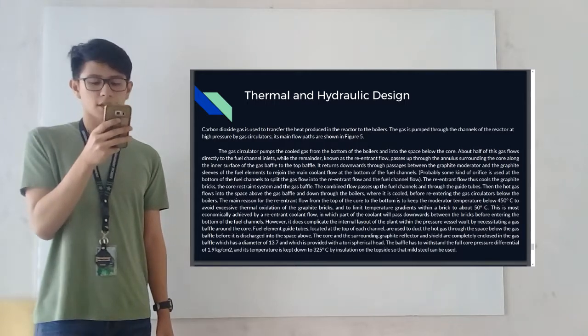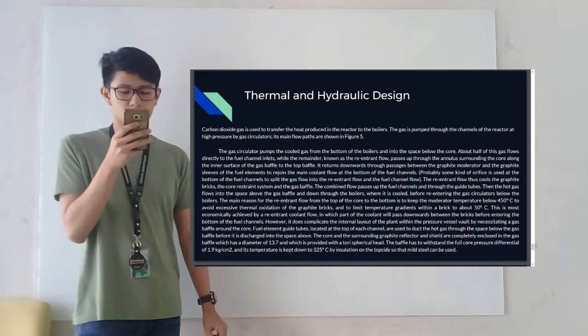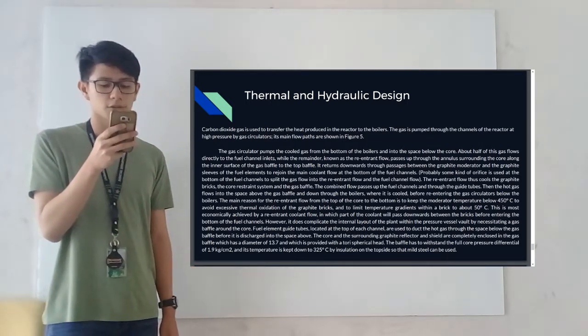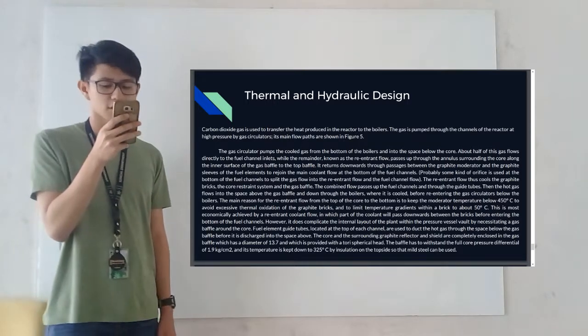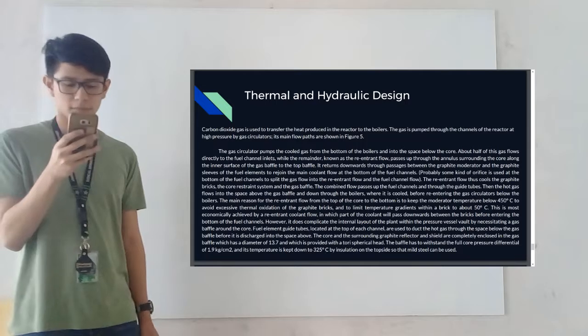The baffle has to withstand a full core pressure differential of 1.9 kg per centimeter squared, and its temperature is kept down to 325 degrees Celsius by insulation on the top side so that mild steel can be used.